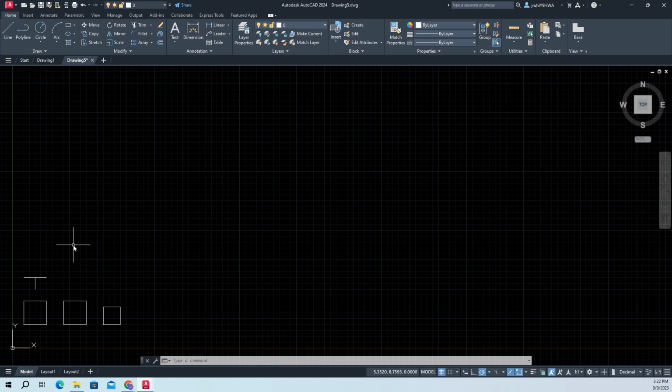So we got to draw two lines, which we're going to extend. So line command. Remember, if it's in the other one, I F12 to get out of dynamic input. 6.5. What is that for? 6.5. 6, comma 6.5. Enter. Another line. Line command's turned on. Then I got 5, comma 5. Enter. My next one is 5, comma 6.